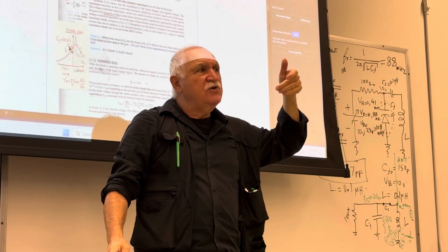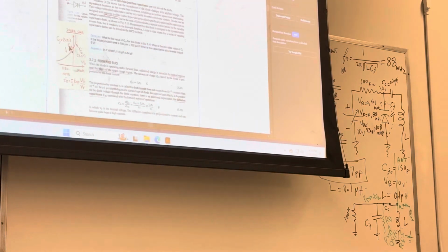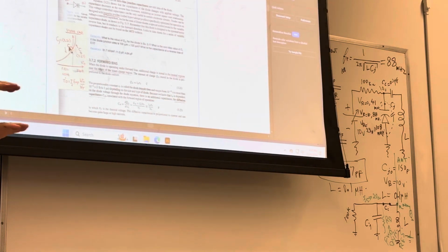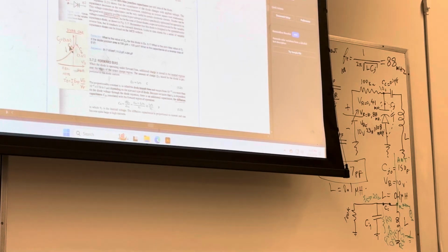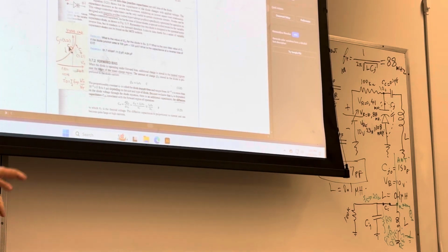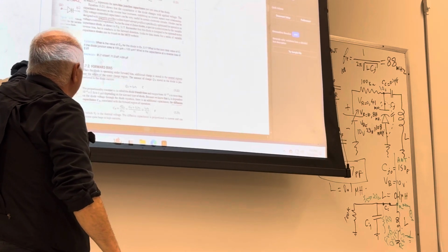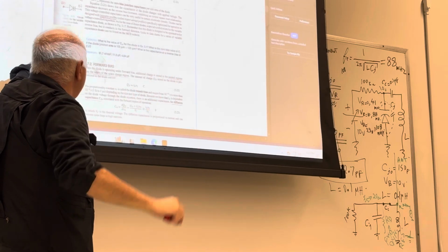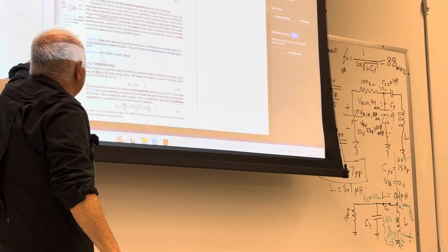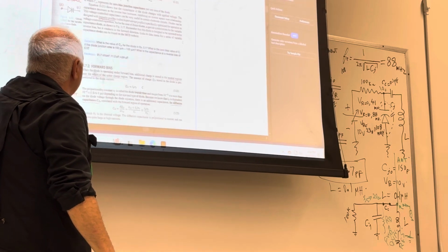When it is in the reverse, you have a charge buildup in the depletion region, which pulls apart and gets close to each other by the external reverse voltage. And that causes a control of the capacitance starting from a zero bias voltage. It means when zero voltage is there, you've got maximum capacitance, going to a lesser capacitance.